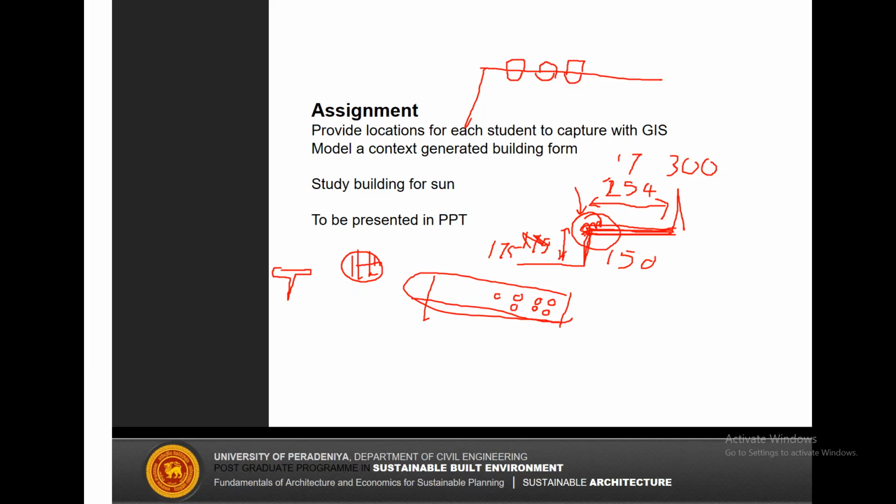Sir, anything about the angle? Staircase angle will be decided by this factor, no? So too, 150 by 300. So if you follow this standard, nothing will happen. So for a publicly used standard staircase, this is the angle we recommend.